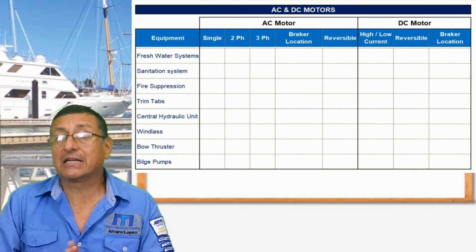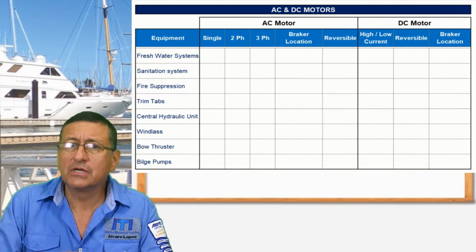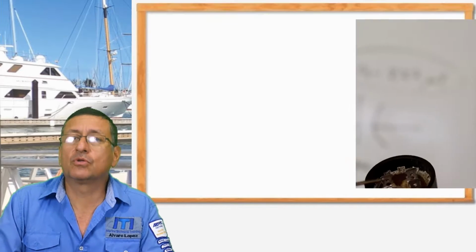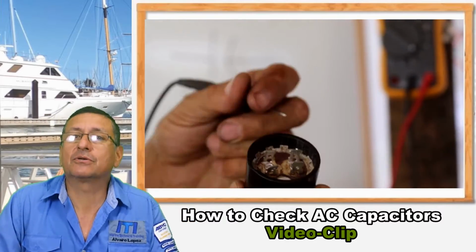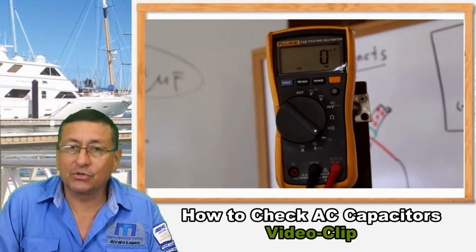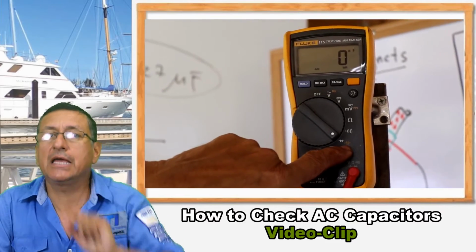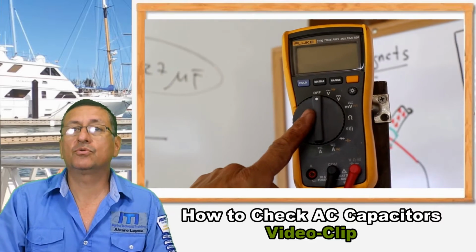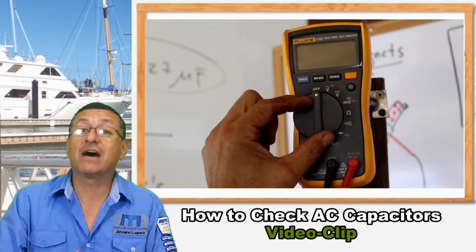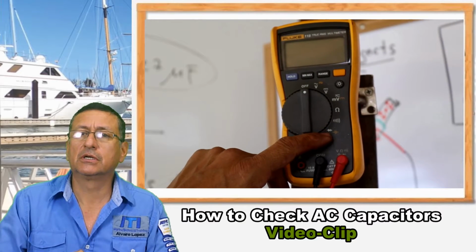And after that, we are going to check a couple of motors. If you have AC motors with capacitors, we are going to check the capacitors. Use the video where I explain the procedure to check capacitors, and try to check capacitors by yourself using the multimeter in the farads mode, and check the condition of the capacitors.